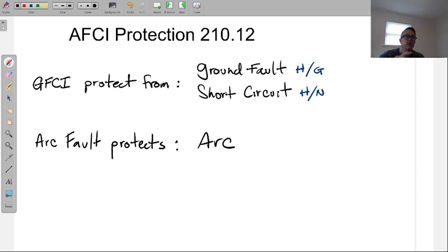That's why I said, your friend calls you over and says, hey, my outlet burnt out. You're like, easy fix. Put a new outlet in. That new one has to be AFCI now. They're like in their bedroom or something. They sell the old ones because you have plenty of places that aren't houses. If a church has a burnt out outlet, they don't have to have AFCIs. If we go to change an outlet at the school, they're regular 120 volt, 20 amp outlets, just buy a regular outlet. It does not have to be AFCI.